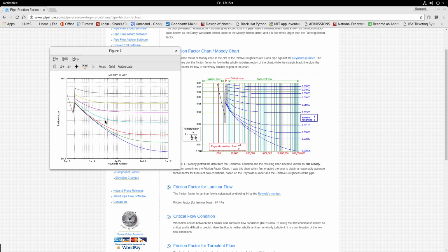So this actually verifies it. You see, this is the laminar portion, a single line going in there, and the turbulent portion starts from here. This is the turbulent portion, and if you cross-check for each of the roughness indices, the values will turn out to be the same as given in the literature. So our Colebrook iterative algorithm is actually verified and validated by this, and you can now use that for design of your pumping system.